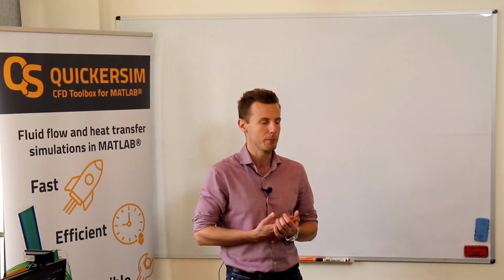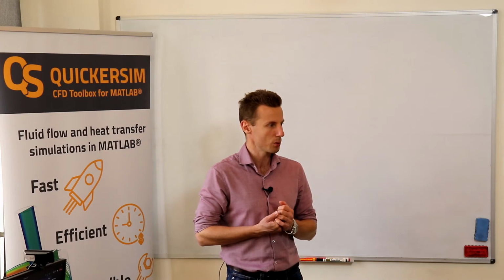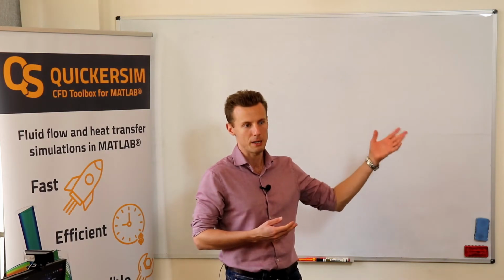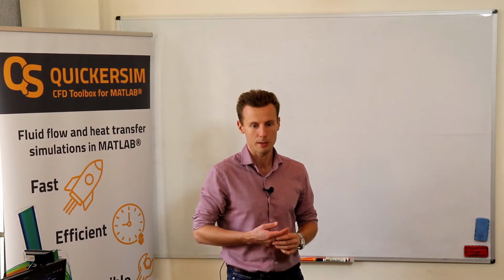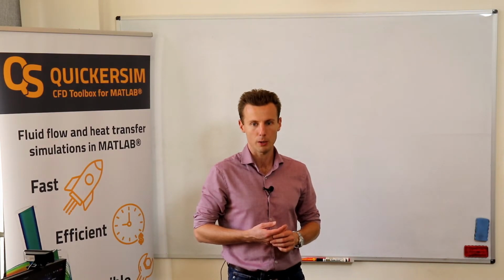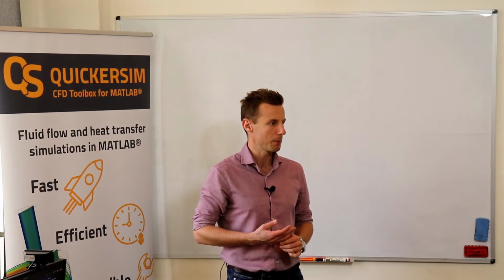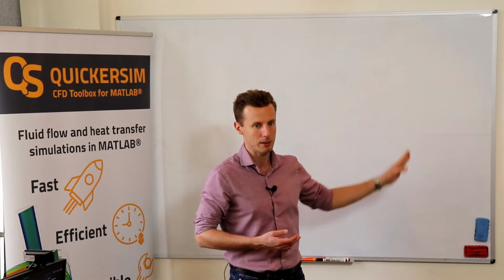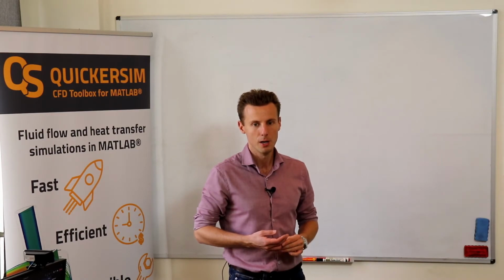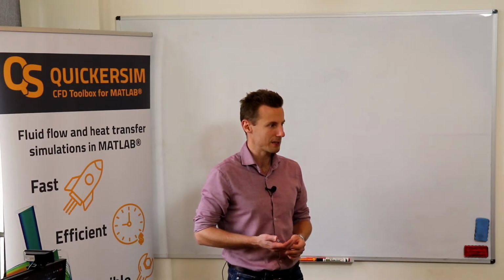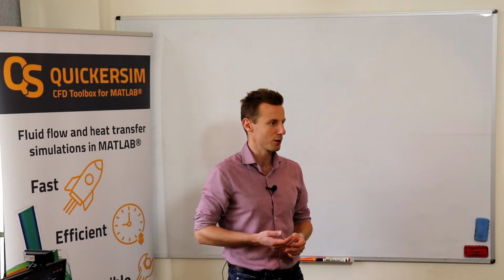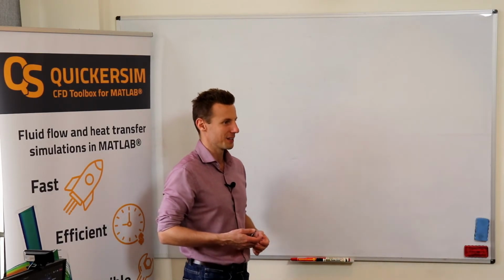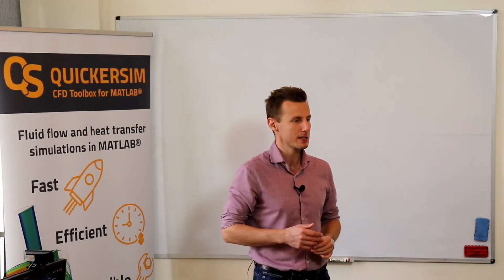Then we have also studied two ways to technically implement these boundary conditions: you can split the terms and eliminate some rows and some columns from the matrix, but we can also do it the other way around. We can basically enter ones on the main diagonal and respective values in the right-hand side vector and proceed this way. And we also stated that these matrices are no longer symmetric, at least very literally speaking.